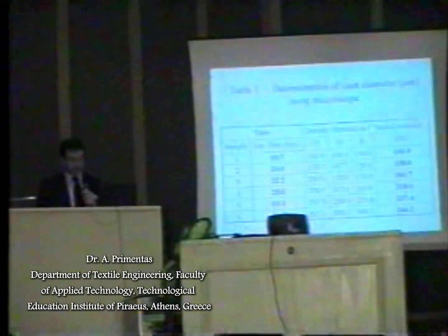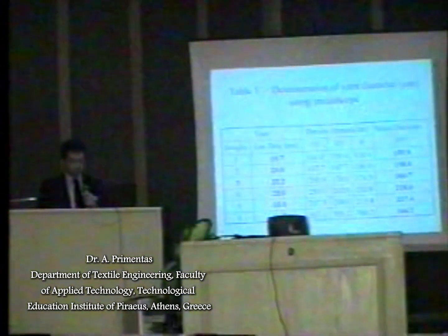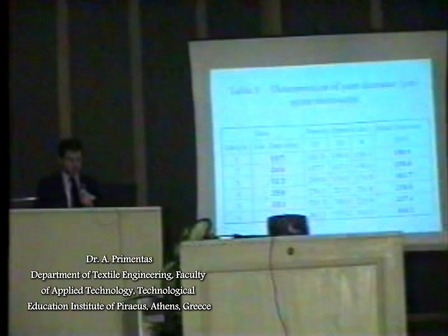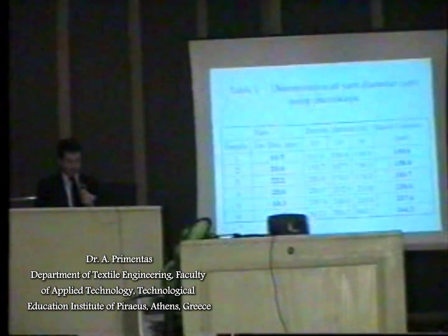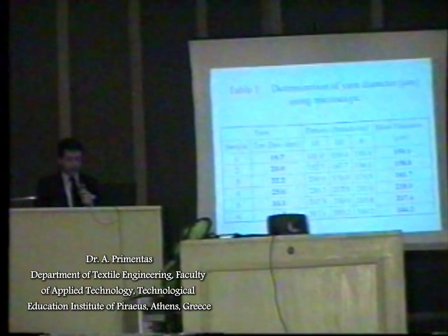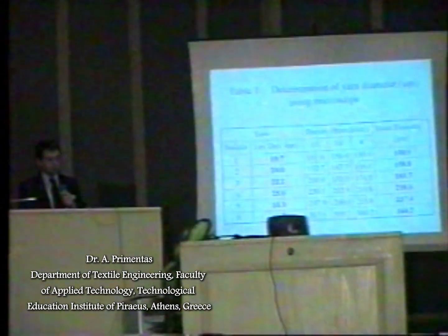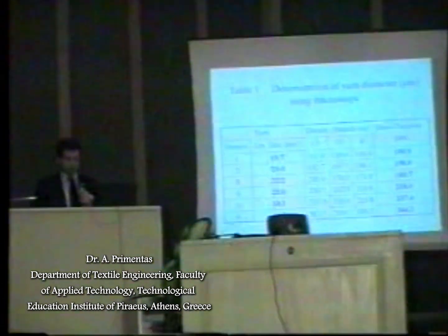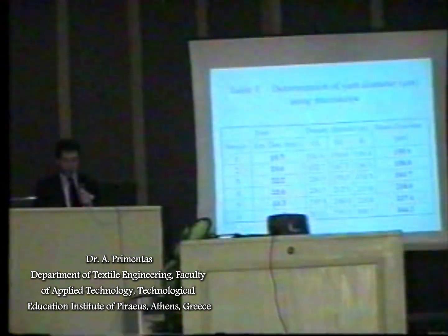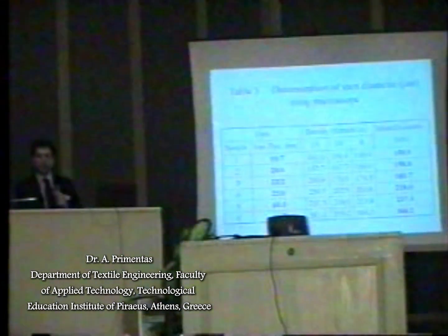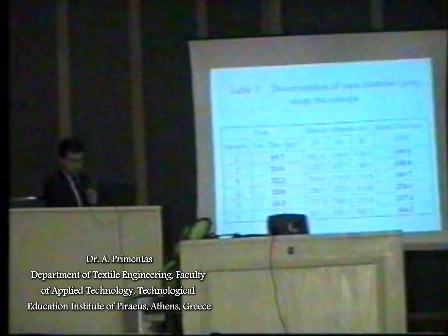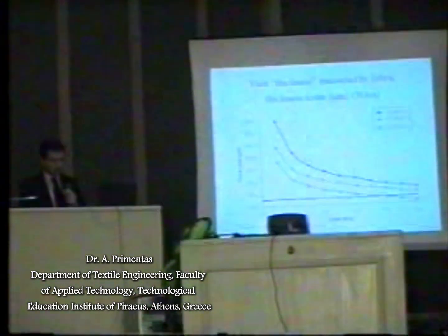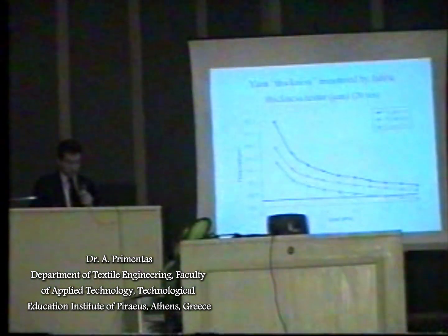After the measurement of the yarn diameter by means of the microscope, the frame with the same yarn sample was placed on the reference surface of the fabric thickness device. Successive tests were carried out by exercising a load range from 0.1 up to 1 kilopascal with a step of 0.1 kilopascal on yarns at 6 different randomly chosen places on that frame. The mean values of thickness/diameter of the yarn with linear density 20 tex are presented in this figure.